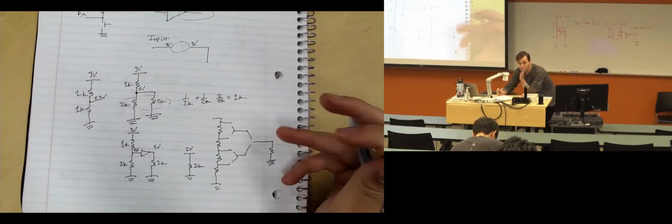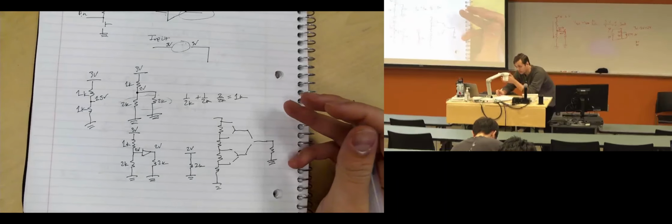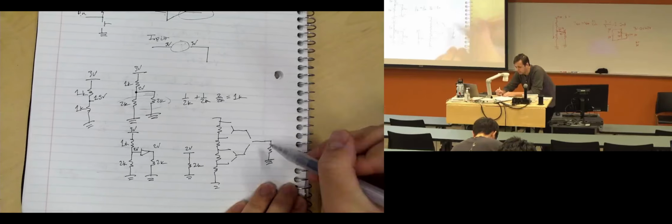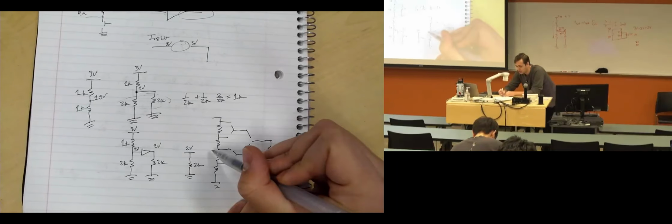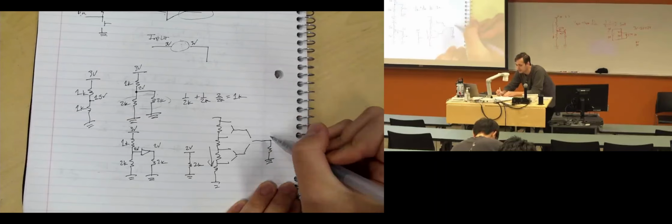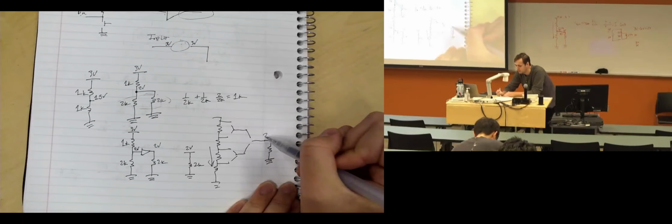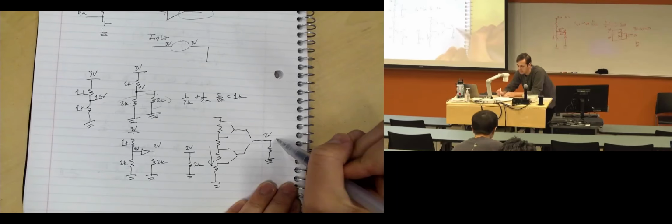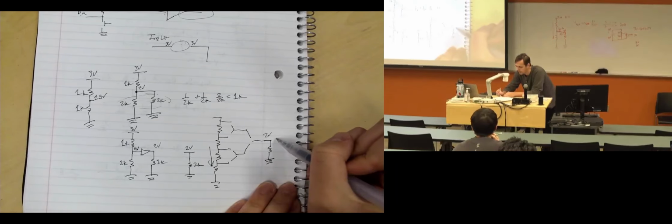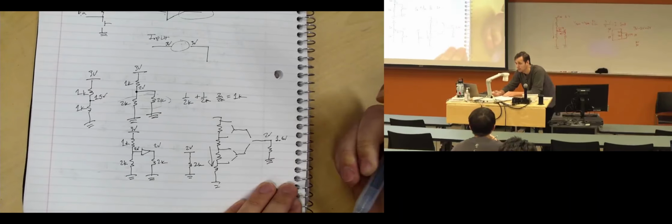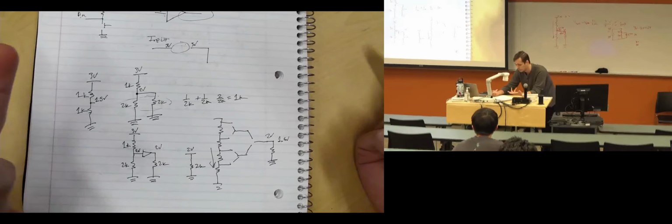As we talked about before, when you have the voltage divider and then you add a resistor onto the output of it, it's going to draw this equivalent resistance down. And let's say you were expecting 2 volts here. It would be lower, right? Because you're adding a parallel path, so maybe it gives you 1.6. That's bad. You want to exactly control it, right?